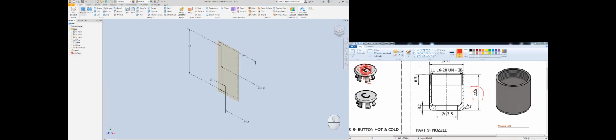finish, make the revolve process, have the fillets. This time it is 2 millimeter from the top side. I will just search the inside feature. For this, I'm just going to change my view to half section view like this to give the thread here. I will just have the half section on XY plane. Again, fillets inside and outside.